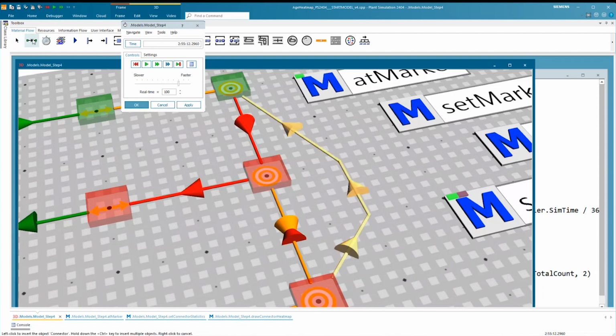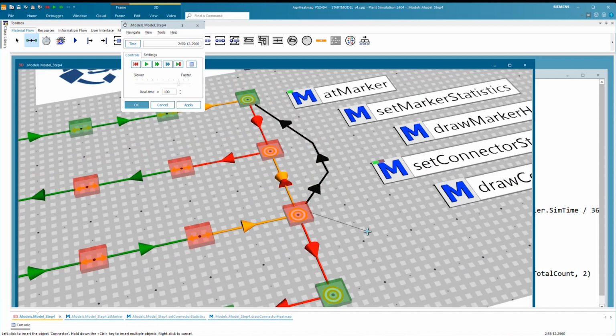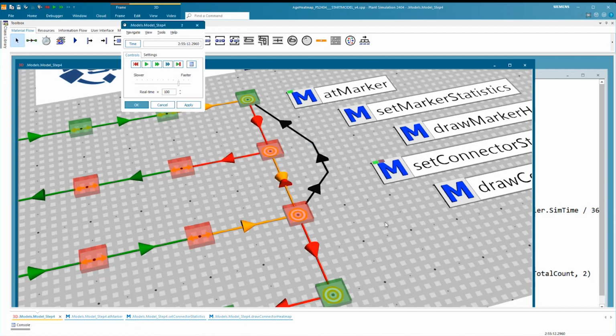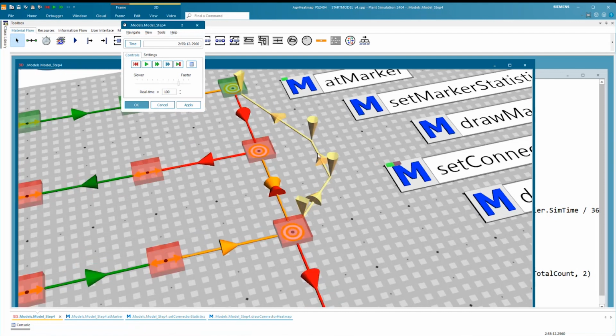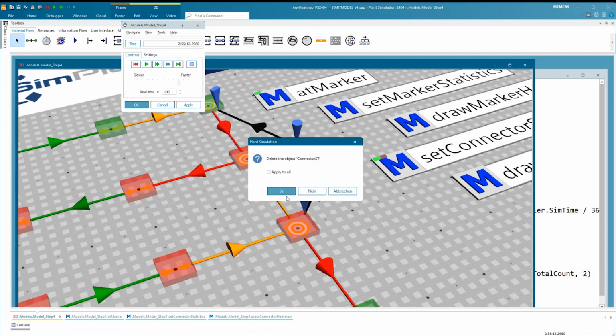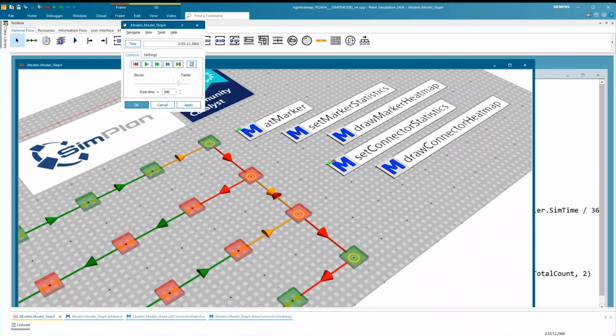So when you create the connector, you first click here and then you press the control key to add anchor points before connecting. Yeah, it already exists. Then you can move them around. I'm not sure whether I can still add them for an existing connector, but that's what you could do if you say this is overlapping and it's not good or clear to see.